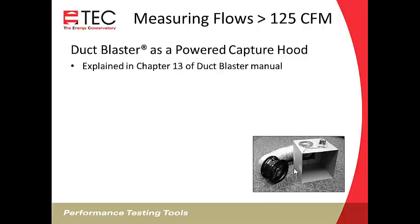So we're going to be pulling additional air out of the box. This is the inlet side of the fan, the side with the rings on. So you'll need to follow the procedure for doing a depressurization test with the Duct Blaster Fan. And for those of you who aren't doing that all the time, you need to make sure you have the flow sensor in there, and the flow conditioner. I mean, you have to have that white flow conditioner with the holes in it, and you need to have 4 feet of straight flex duct before the air goes into the fan, so you're straightening out that airflow before it goes across the flow sensor.